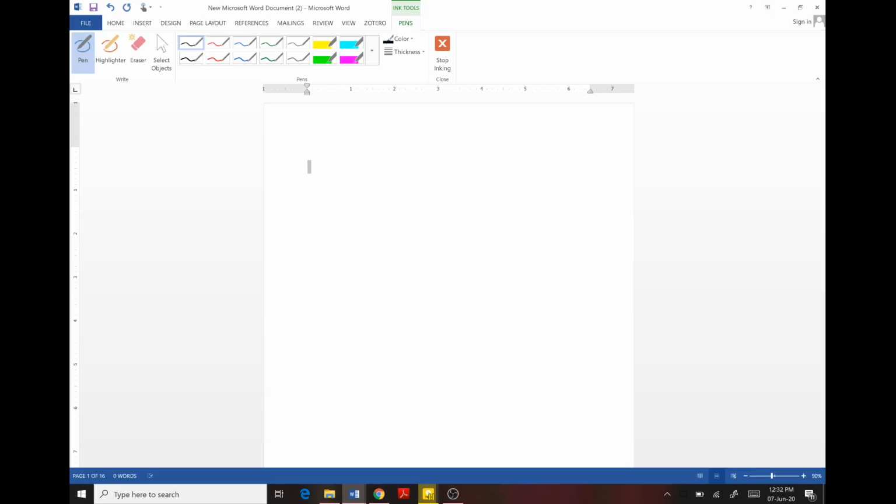Now, for case 1, when wall is entirely dipped in cohesive soil, design of sheet piling in cohesive soil is complicated by the fact that the strength of clay changes with time, unlike the cohesionless soil, and the lateral earth pressure also changes with time. The depth of penetration and the size of piling must satisfy the pressure conditions that exist immediately after installation and after the long-term conditions. The strength of the clay has changed.